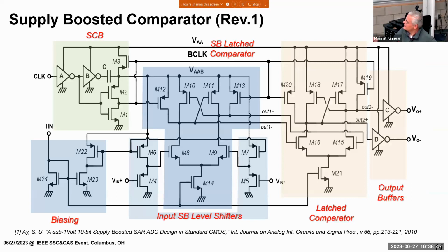Because this node has different junctions, right? Yes. And there is a mismatch from here to there, from here to there, on that junction. The more this goes down, the higher that sensitivity. And that became an issue, yeah. Both drop, and they may drop in a different way because of the mismatch, so you have to be careful about that. But again, we are not building a 12-bit ADC. Yeah, you should be fine.